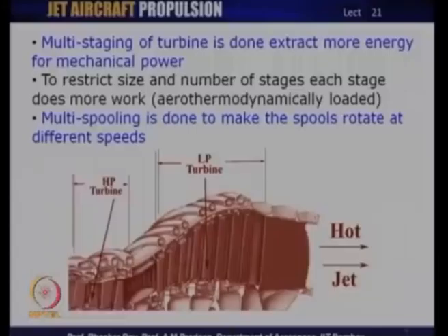However, very high supersonic speeds even today are not very comfortable, both for the designer as well as in operational conditions, and as a result, compressor and fan designers try to avoid very high supersonic operating speeds through these compressors. Now, to restrict this fluid dynamic speed through these compressors, the compressor rotating speed needs to be limited to certain values.